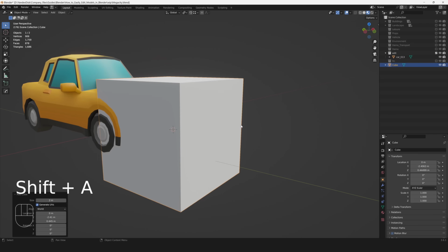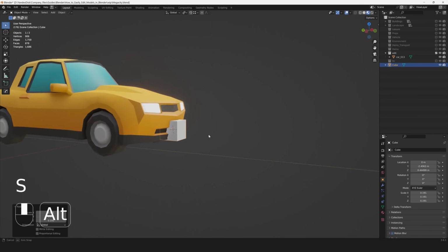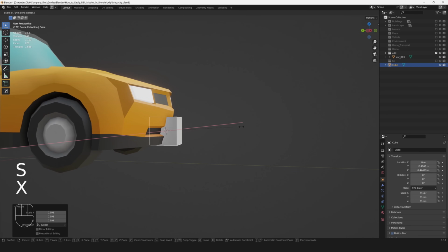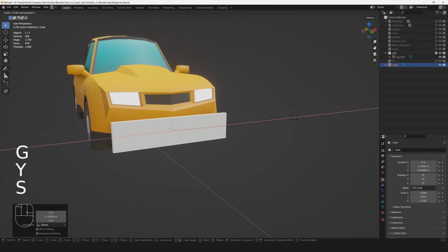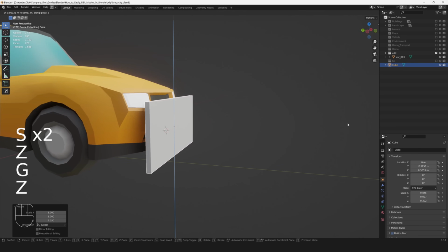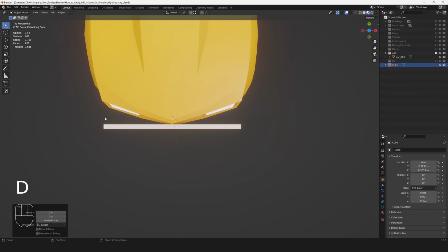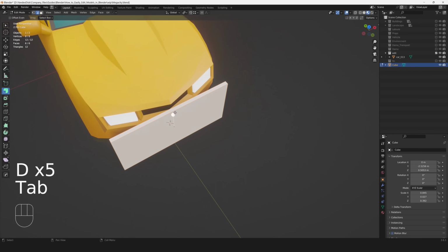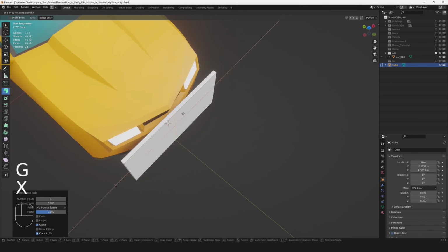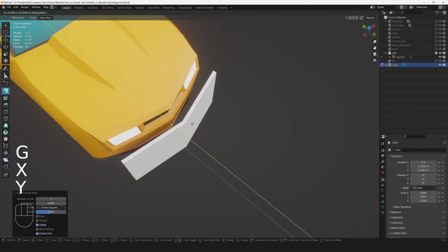I will select some kind of segments and place my cursor here. And now when I tell Blender to create this object, it creates it right there at the 3D cursor place. I will scale my cube a little bit. Yeah, I use different axes for this because I need to deform it. I should make it not that flat, but a little bit sharper. To add a new edge loop, I should press Ctrl plus R and then left mouse button to apply this.